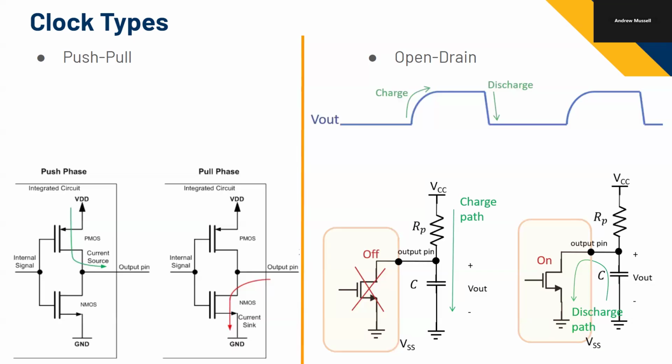And so for an NMOS, when VGS is greater than the threshold voltage, this will turn on and start conducting. There's a little bit that I'm skipping over where there's intermediate areas where you could use it as an amplifier instead of a switch, but let's just talk about it as a switch for now. So when this voltage is above the threshold, this will be shorted and connected. So that would mean that this is really high, right? If we connect this to VDD, it's going to be a large voltage here. This will be connected.